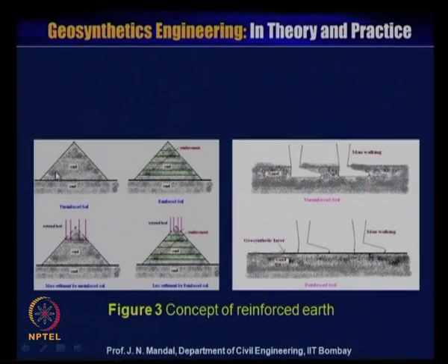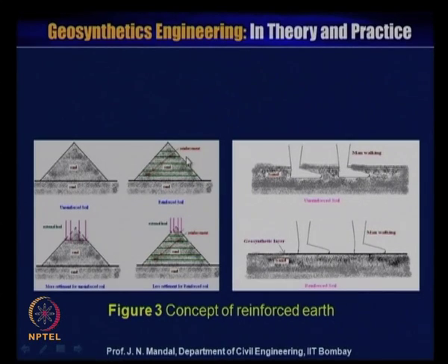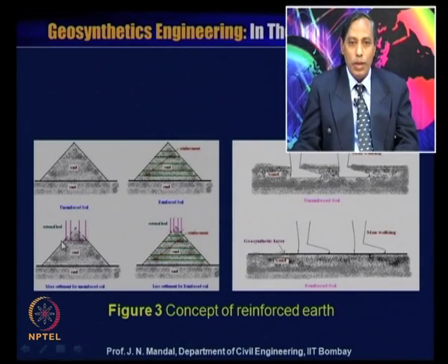Look at this figure also. This cone is the unreinforced one, and you can place a number of layers of reinforcement. If you put a load on this, you can see the formation of the cone after the application of the load, but when you introduce layers of reinforcement, you can see the difference in settlement, and also the difference in the load carrying capacity of the soil.